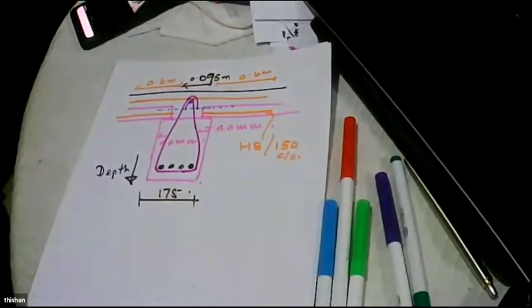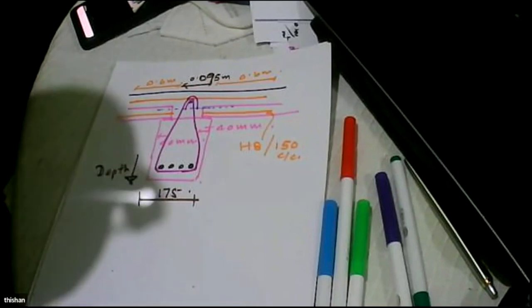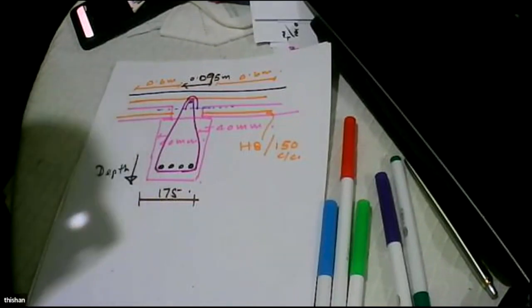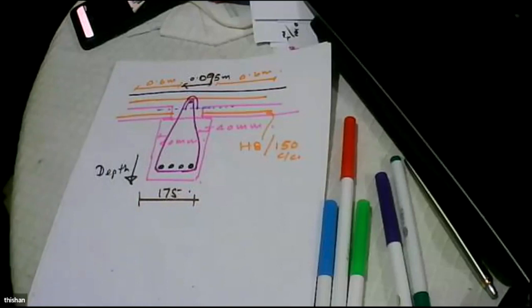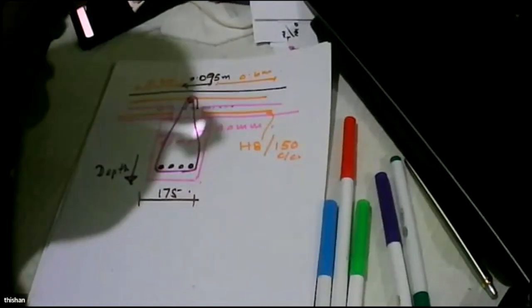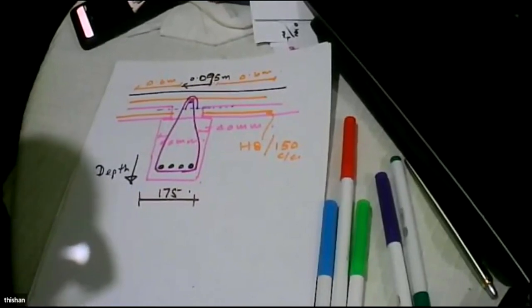No, 95 millimeters. That will allow us to fix this reinforcement very well. Is that clear, Bandhuka? Yes, that is clear, sir. Great. So this is a trap system. Then depending on the span, in a similar manner, considering it as a flange beam, we can design the beam as well. That we'll discuss next day.